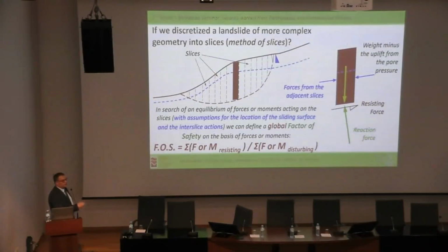eventually get something wrong with the position of the estimated critical surface. Because it is not just a matter of finding a number and we are comparing just the total factor of safety with the same result that we would be obtaining from partial factors, but when we are carrying out an analysis like this, the actual values that we are using in our calculations are going to affect the position of the critical sliding surface that we are considering.